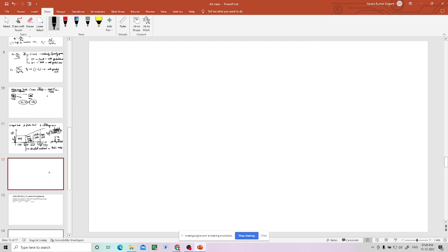Suppose I have given a soil, let us say kaolin clay. I have given you this dry sample. Then I ask you what is the liquid limit for this clay. Means how much water should I add so that this will reach its liquid limit. So to find out plastic limit, liquid limit, and shrinkage limit for a particular clay, you have to do some laboratory experiments. Those are called liquid limit test, plastic limit test, shrinkage limit test.